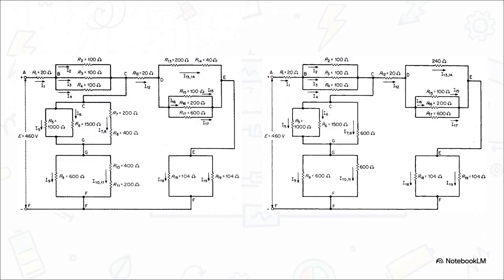And boom, here's our first move in action. Check out the left side. See those resistors, R13 and R14? They're in series, just a single path. So we just add their values, 200 plus 40 ohms. Now look at the right. They've been replaced by one single equivalent 240 ohm resistor. With just one simple calculation, the labyrinth is already a little bit less scary.